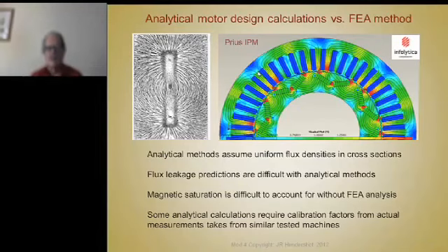So you can go to a higher order FEA solution, which just increases the number of elements, and that smooths up these equipotential lines. It didn't really change the torque or the final result all that much, but it sure makes you think it does. It looks more uniform, and it certainly looks better in your report. Although having said that, you still can get some errors through too coarse of a mesh.